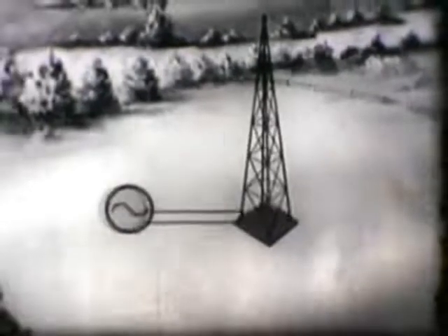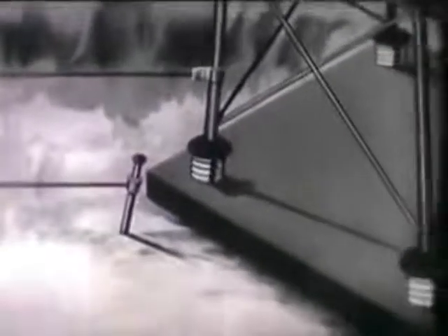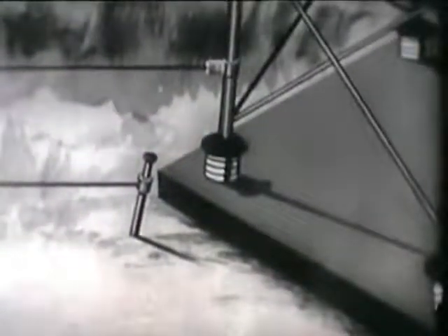Our source of power becomes a transmitter, which is located some distance from the tower to prevent distortion of radiation patterns. The efficiency of a quarter wave antenna depends largely on the nature of the ground. At installations near the sea or in salt marshland, the Earth's conductivity is excellent, and a simple metal stake provides proper ground.